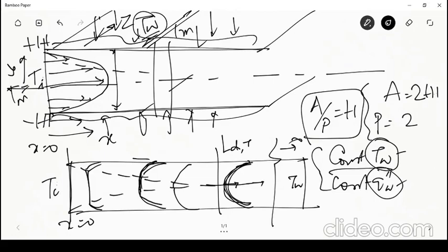But something else happens when the boundary layers meet. We'll understand what happens by analyzing the equations at that point. Even if the heat flux is constant, in which case the wall temperature will continuously be changing from the inlet onwards, and the bulk temperature would also be changing, there will be a dynamic equilibrium between the heat that comes in and the temperature profile that changes. So there is a developing region and a fully developed region. First, let us concentrate on the fully developed region and understand what can happen in that region.